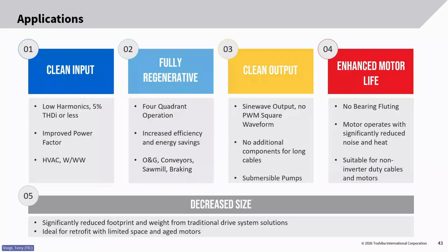So to kind of review all of the different applications for the WC1 where we see it fitting the best, clean input. So specifically what we're talking about here, low harmonics, right? So for the HVAC water wastewater world where harmonics are a big concern, the WC1 would be a great fit.